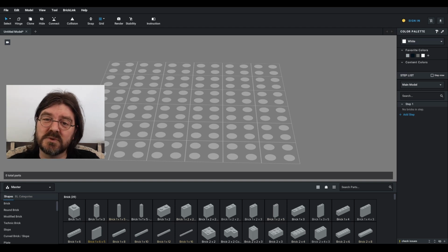Another thing about the Connect tool is sometimes Snap does not always work perfectly and your connections can be off by a little. The Connect tool can alleviate that problem, which is very helpful. It can also be used to accurately place rods, axles, hinges, and ball joints. So it's really a versatile tool to have.